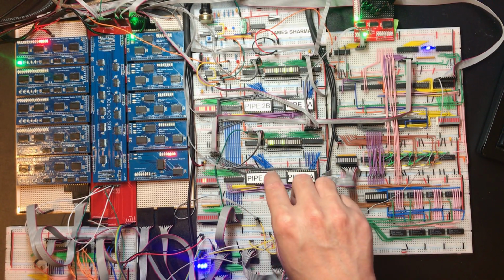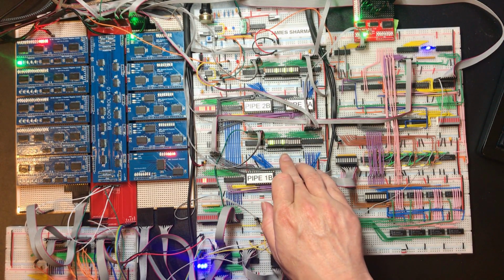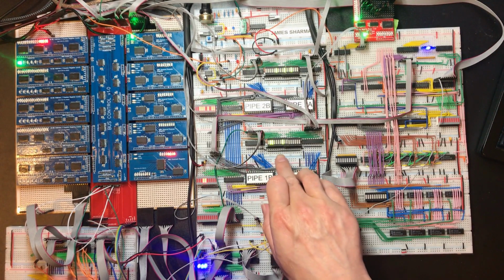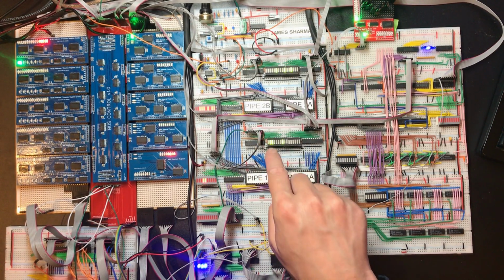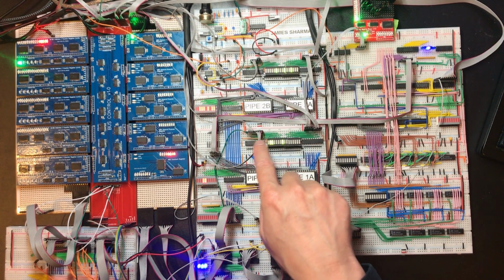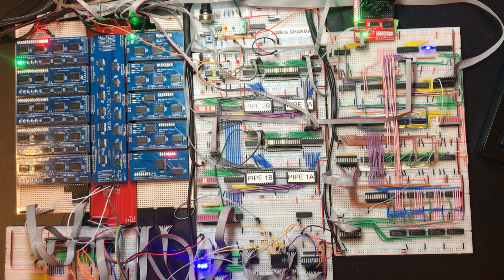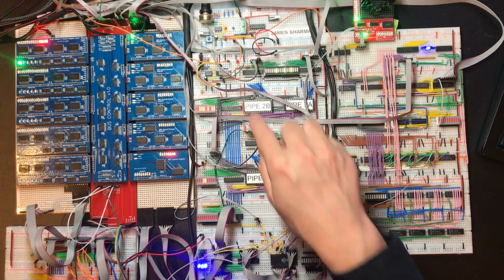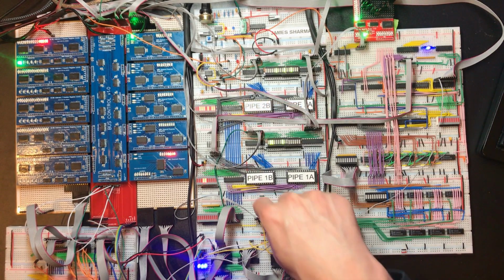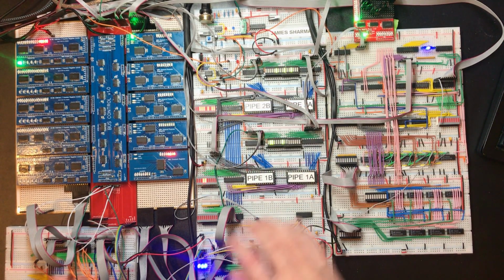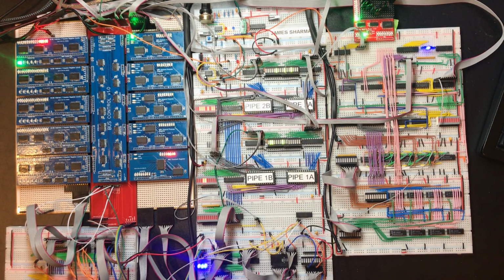We could also generate that control line because we know the address of the program counter, so we could build a little logic circuit on these 4 lines here, which are the load address on the transfer bus, and say if that's 1, which is the address of the program counter, then we don't want to increment the program counter here. So that could work as well. But if you remember, we did have an issue with this, which I still want to spend some time diagnosing, when the bus request line was going through this OR gate. Whatever we're doing there, it needs to be pretty quick, and we probably need to address the timing overlap there before we do anything else.